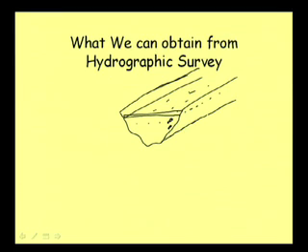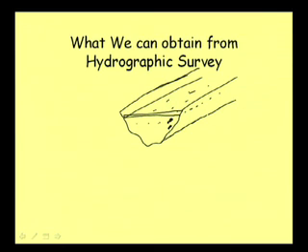The current meter will be mounted on a vertical rod, and we know the depth at which we are putting the current meter and what velocity we are measuring. Then when we are moving in this direction, we put it here and here, or maybe here. Like that, at different points we put the current meter and measure the velocity. Now, from this record, what sort of problem can we have when we are moving along this? We need to keep our boat fixed here, that is one problem.